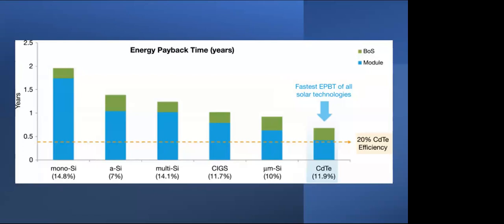People think about the energy payback period. The meaning of energy payback period is that we require some amount of energy at the production of solar PV or some other product. The silicon process requires a high amount of energy because of the high temperature process. The material conversions are very energy intensive processes for a solar panel. The same amount of energy required for the production stage that can be generated by that solar panel, we call that the energy payback period.